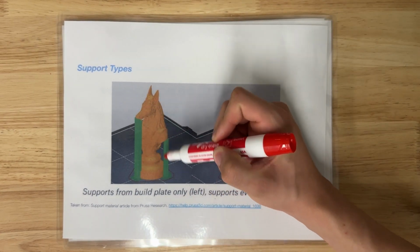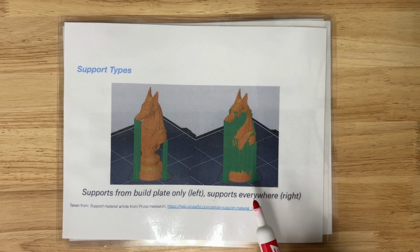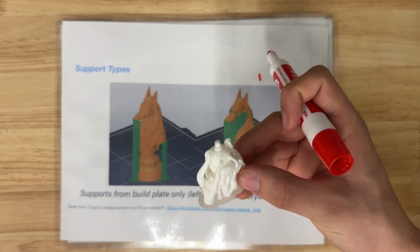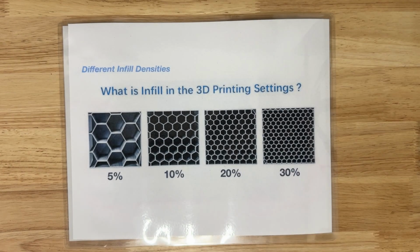So we put in these green supports when slicing. This is support from the build plate. It's cheaper and faster than everywhere supports. This has a little bit of a higher success rate, but it's a lot harder to clean up. In the future, we can start getting into organic supports, which are new and they're excellent for making quick, cheap, and easy to remove supports.